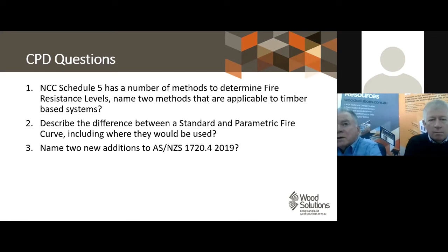And the fourth assessment method is a comparison of your proposal's result with the result of the application of a deemed to satisfy provision. So if the deemed to satisfy provision was to produce a result that equated to the number 10, then the NCC says, if you can demonstrate that your performance solution will also achieve the number 10, that's a means of determining compliance with the performance requirements.